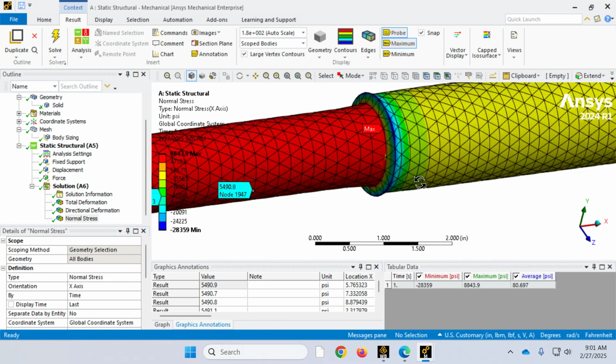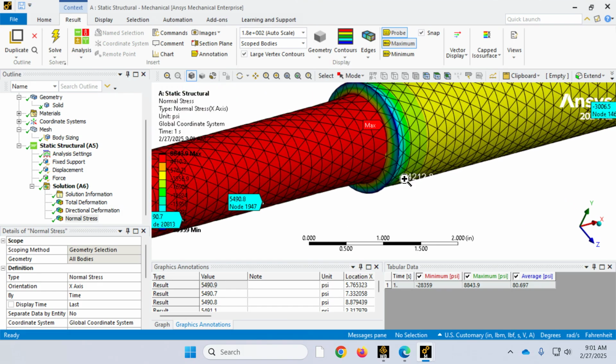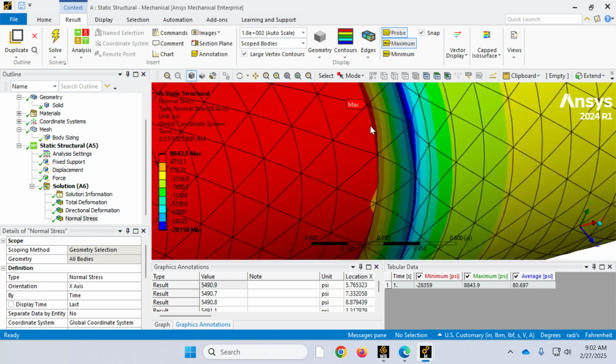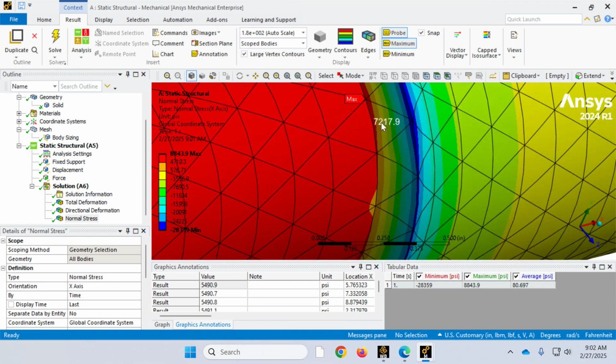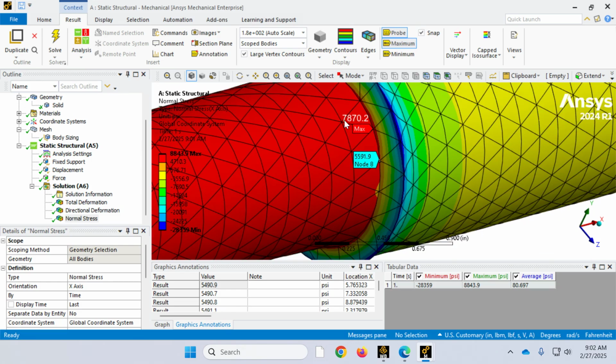If I zoom here, you see that we do have some stress concentration where there is a change and where the force is applied to the edge. And if you look within the element, I see multiple stresses at this transition. So this is a numerical error and should not represent the stress that you're going to see in your part.